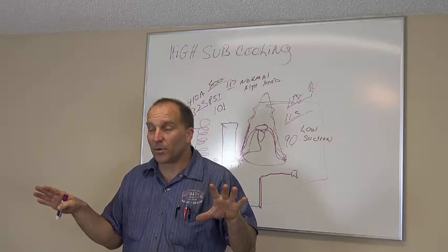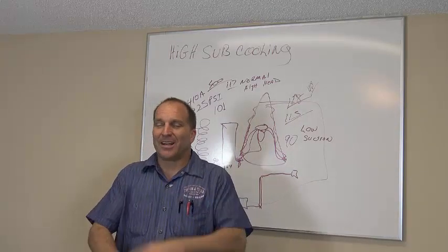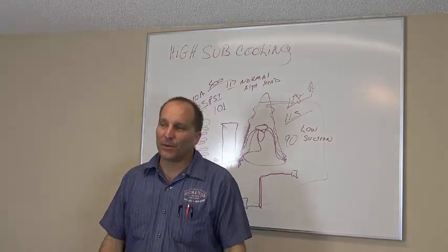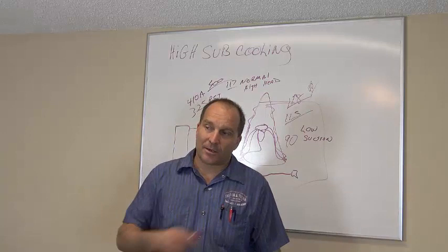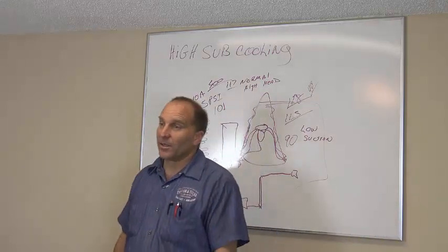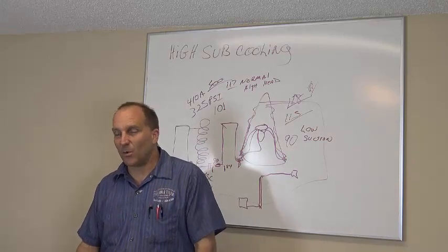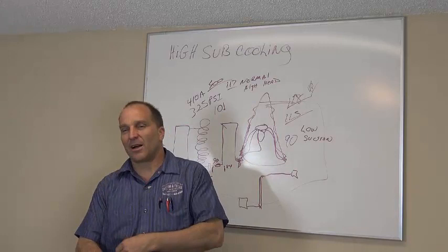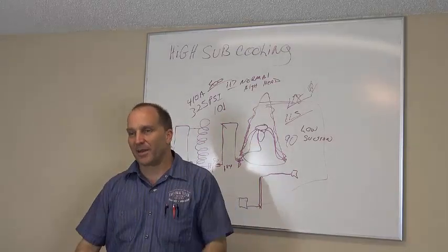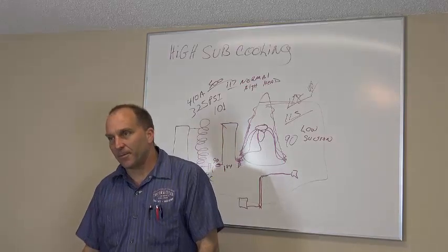I'm sorry, a low subcooling. And you look at the condenser and it is completely filthy dirty. So you tell the customer, man, I've got to clean your condenser. He goes out there and he sees it. He watches you clean everything out. You're pulling leaves out of it, you're hosing it out, and dirt and grime are just coming out of it. Man, he's well worth cleaning this condenser, right?